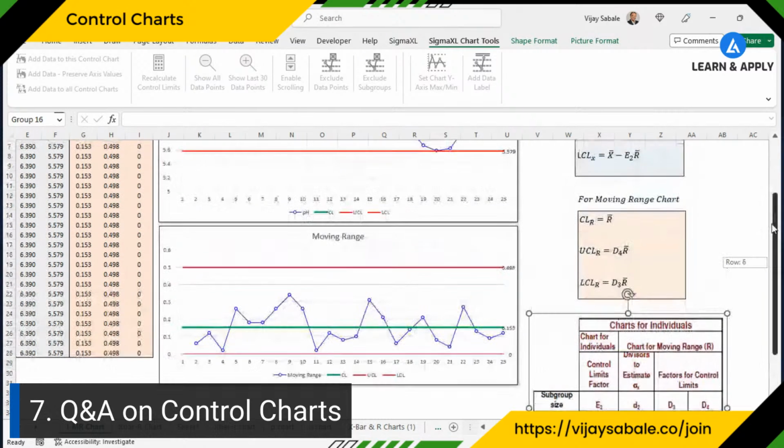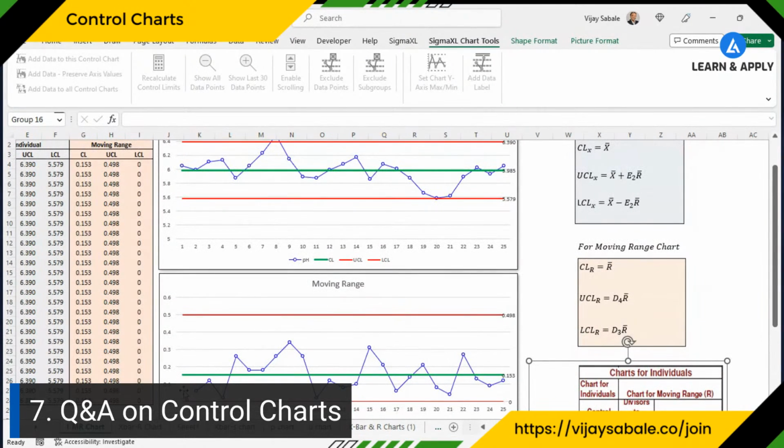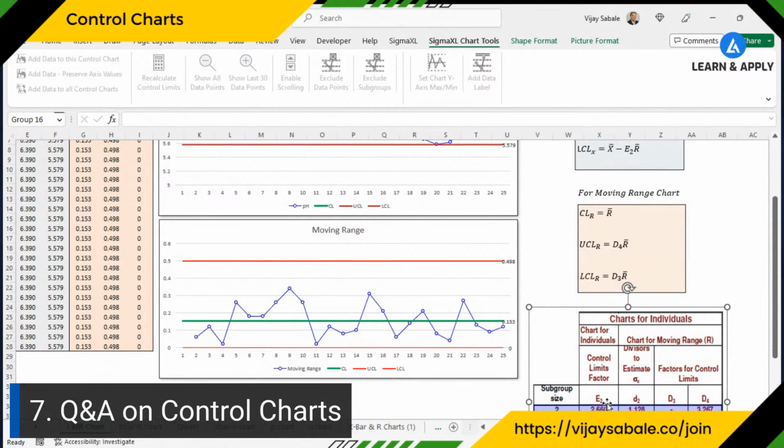For example, if you go to the range chart, here we can see the first data point is missing because we have one data point collected at a time, so we cannot calculate the range there. But we can calculate the range for the first and second data point. So the range chart starts from point number 2, because the range for point number 2 is the difference between observation number 1 and observation number 2. So the range chart starts from point number 2, considering the subgroup size as 2. So we consider the E2, D3, and D4 constants for subgroup size 2 for the range chart,